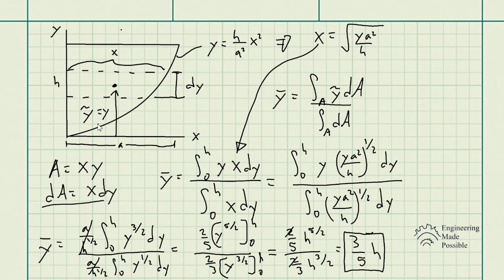And it's the same if we're talking about the cross section of a beam, then you would go about it the same way by using the formulas that were shown in the beginning. So it's definitely very useful to know, because you have real world applications when it comes to doing your analysis on certain systems. You should be able to determine the center of gravity when it comes to certain objects. So you could apply the external forces or the weight of that object, as well as it'll help you do your calculations for any other kinds of analysis. So this is how you solve for the centroids of an area.